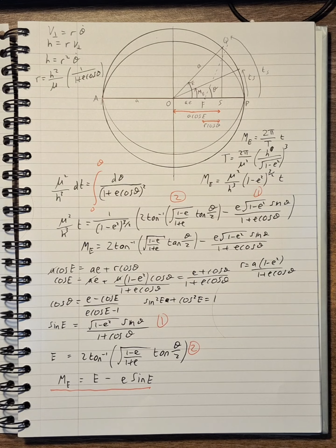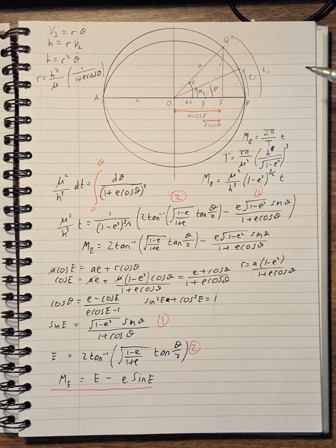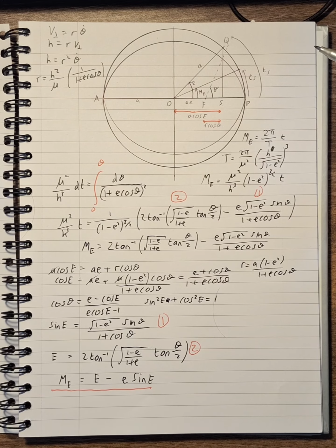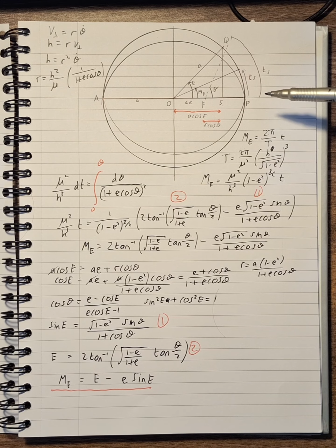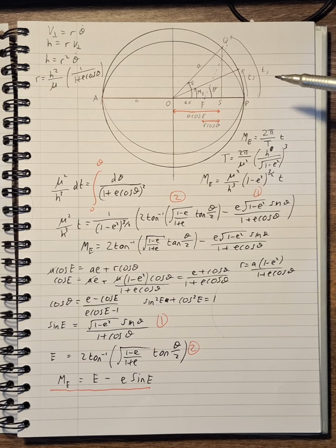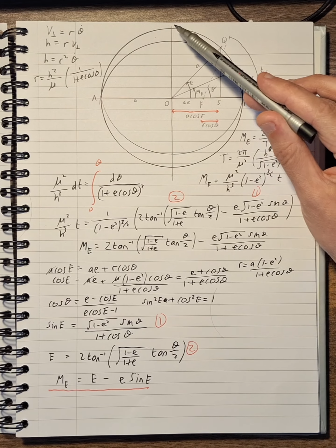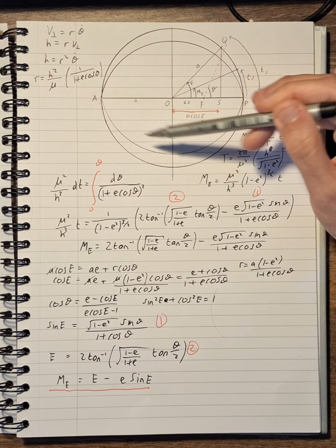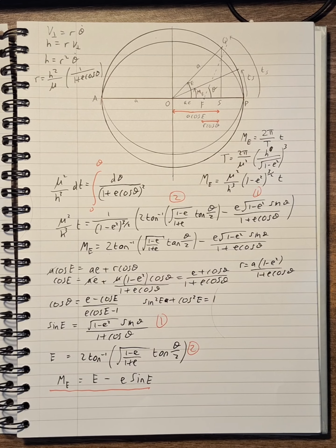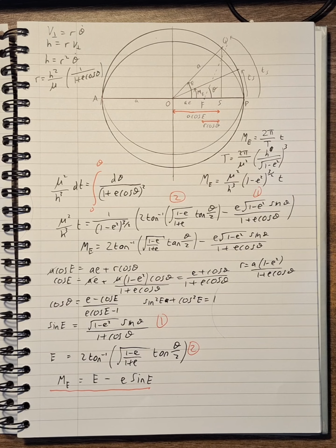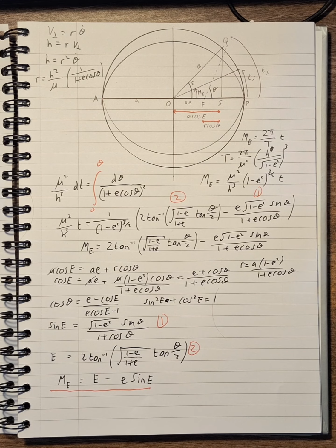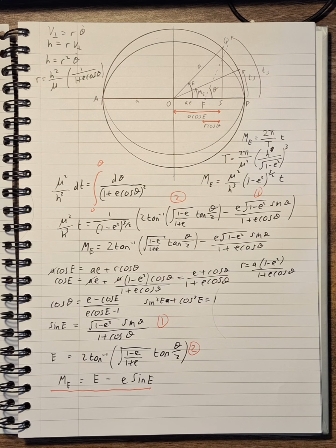So let's get started. To get the time of orbit, you need to use a few tricks with trigonometry. The trick generally used is to draw a full circle around the elliptical orbit and define a concept termed the mean anomaly, which is the angle covered in the same time period as the elliptical orbit.